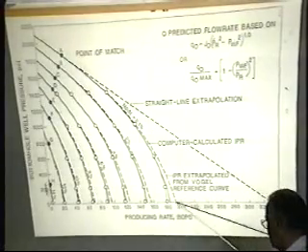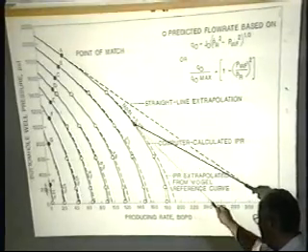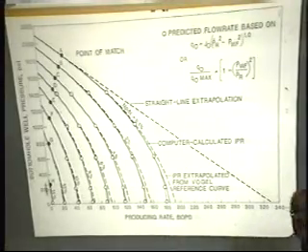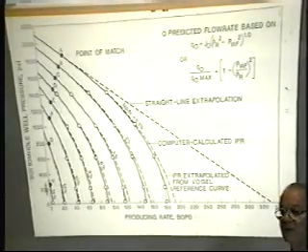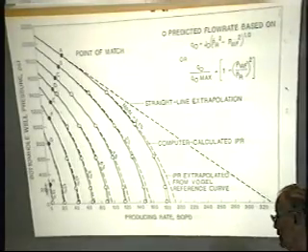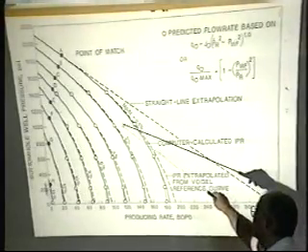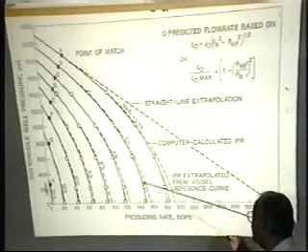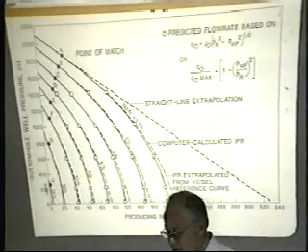For practical purposes, there isn't much difference in the answer here, but conceptually it says that the delta P squared form equation fits his reservoir simulation model better than his empirically backed out inflow performance equation. So from a production engineering standpoint, there isn't much difference, but again, you also see that at different stages of depletion this curve continues to move, and again, the delta P squared fits all the way. It's a better representation of the inflow performance.